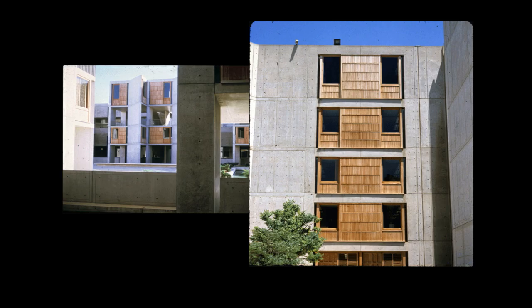Or what they also discovered is that with some framework, you can connect both sides of the formwork with tension rods. And so the way that became common for building reinforced concrete walls was to build framework with plywood slabs to the inside of both of those parallel walls. And then you would run tension rods from one piece of lumber on one side of the formwork to a piece of lumber on the other side of the formwork.